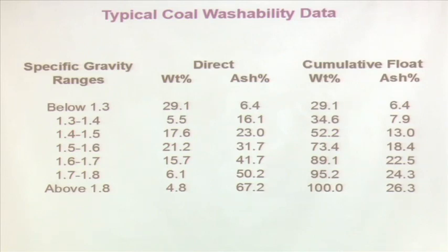Now what can we do? From these samples, I can take representative samples and do the ash analysis. Very simple one. You burn it at 825 degrees centigrade for 1 hour in an oxidizing atmosphere. You take it out and see how much material is there. By the weight loss method, you can get the ash percentages. Ash is basically one quality assessment parameter, the more the ash, the lesser the value. So then I get to know, because it is the 1.3 float, that means we are very close to the carbon-rich part.